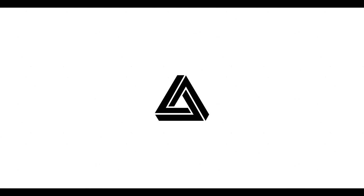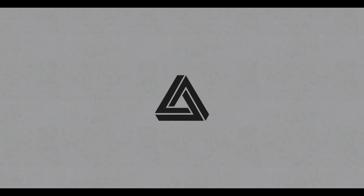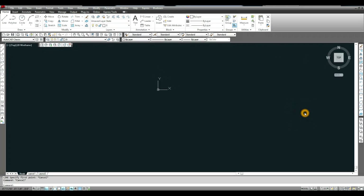Hey Design Nation, in this session you're going to learn how to make flippable dynamic blocks in AutoCAD. So today we're going to construct a door and we're going to change the location of the swing.